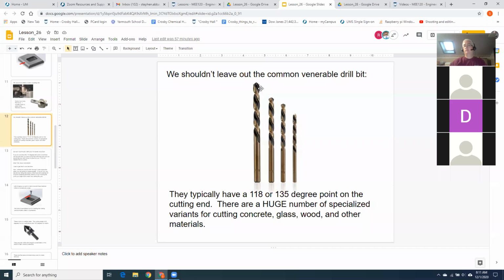Or can I use a common drill bit? This is very, very fast. Whereas milling a flat bottomed hole can be done, but it's just a lot more time, therefore more money. So if you need to make a blind hole, have the cone at the bottom, make sure it's there. Otherwise, somebody's going to come talk to you.